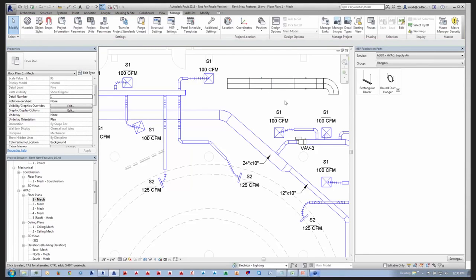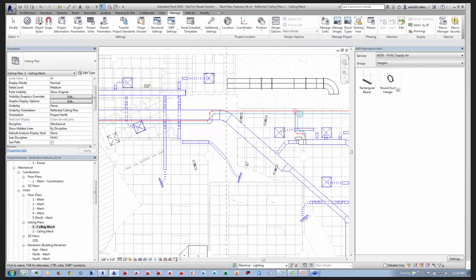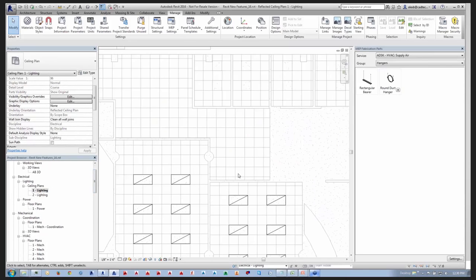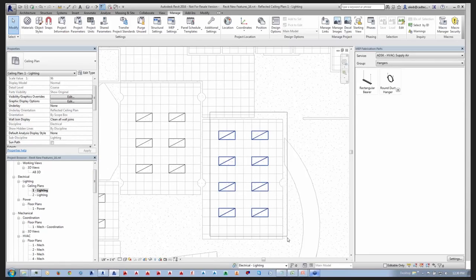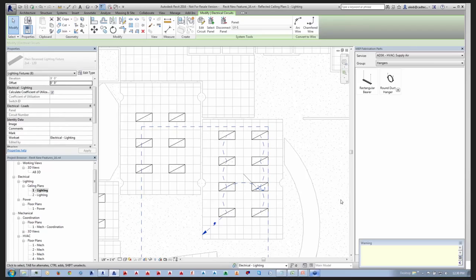And now I'm just going to talk about a couple of the R2 enhancements that I've been using that I think are really great. One great R2 enhancement, I'm going to go to a lighting plan here to show you this, is that now when we are circuiting, the panel that you're circuiting to will be remembered.